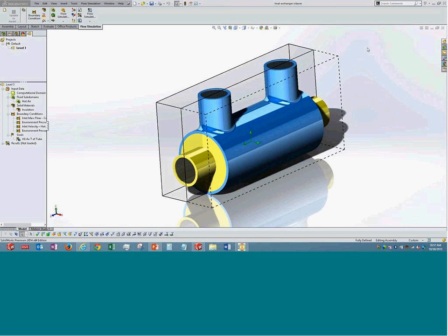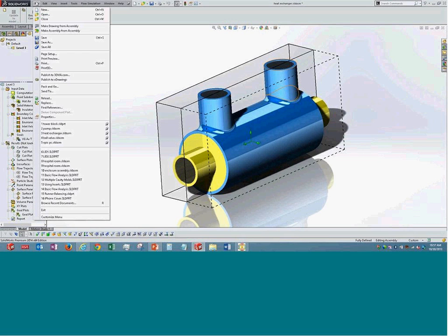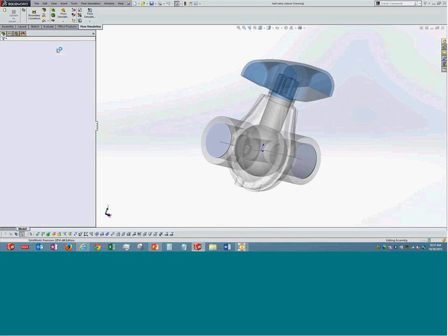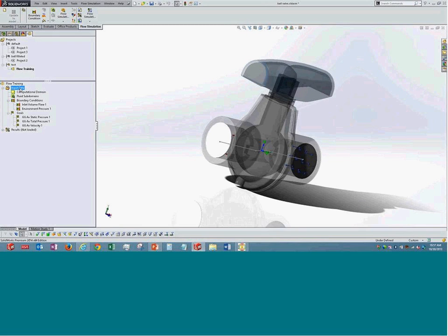I unselect it, and then I can specify the details of the mesh. Over here we have different options, like we can specify the number of elements across a certain length in the other direction or between a certain area. We can also have other details, like I can give a local mesh refinement over here. Let me show you the option.